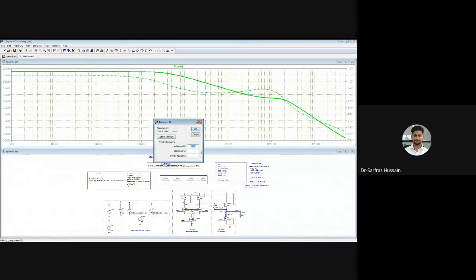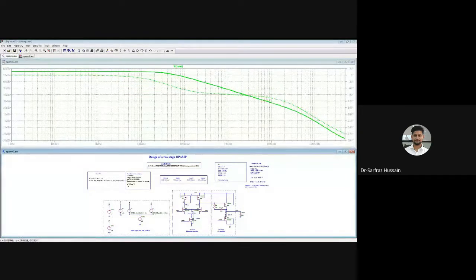So what I'll do is change my resistance value. Since 100K is too much, I will reduce this one. I'll make it 1K. Since it is moving, if I keep it 1K, then also I am getting this one. Like this you can keep on changing these values and see which gives you the stable value, or you can directly calculate from the formula.